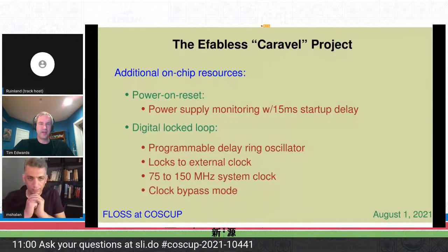The user project area is contained in the harness chip's design files as an empty wrapper. It's not completely empty since it has all of the pins that the user area can connect to, including the GPIO control and data lines and the whole logic analyzer interface, and the extra clocks, reset, and interrupt signals.